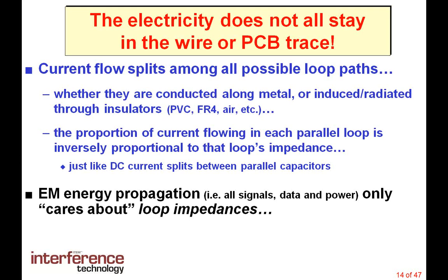Remember, electromagnetic energy propagation, in other words all signals, data, and power, and of course noise, only cares about loop impedances. It doesn't care whether it's air or metal or whatever. All it cares about is the impedance.